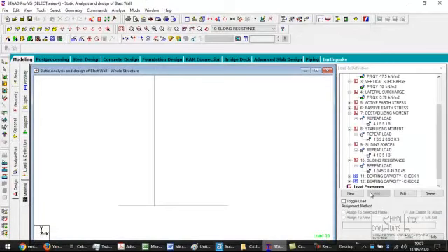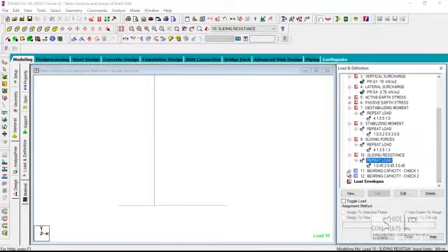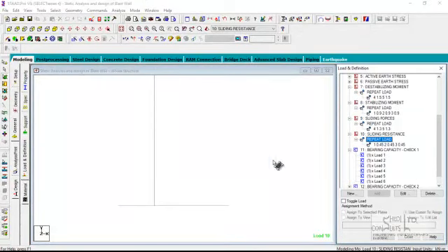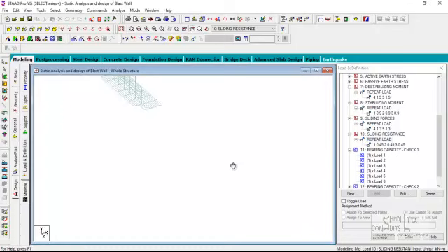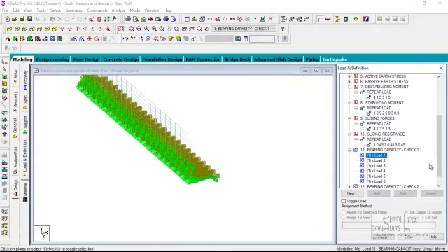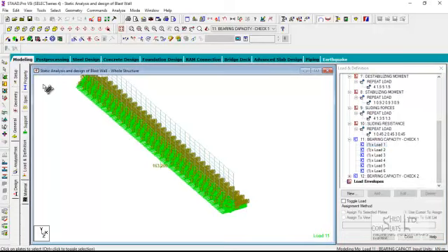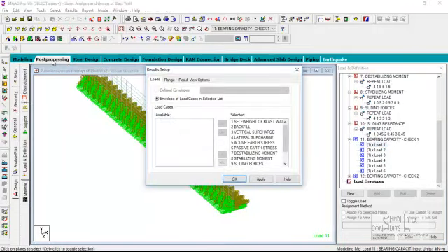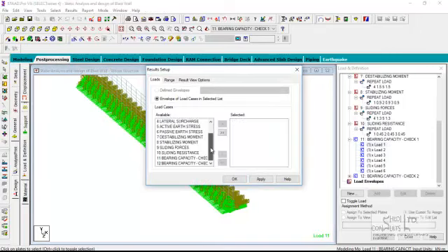So when we had this, we now also check the bearing capacity failure at serviceability limit states. We already have the allowable bearing capacity of the soil. We then did the load combination, and then ran the analysis. At the completion of the static analysis, let's look at the outcome.